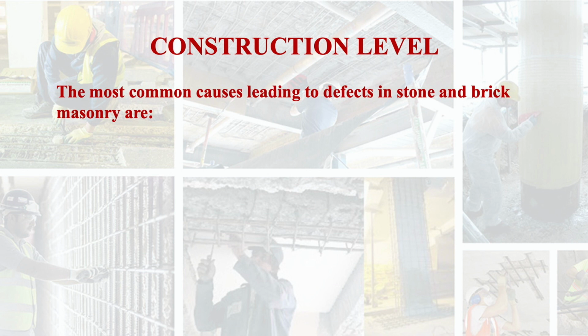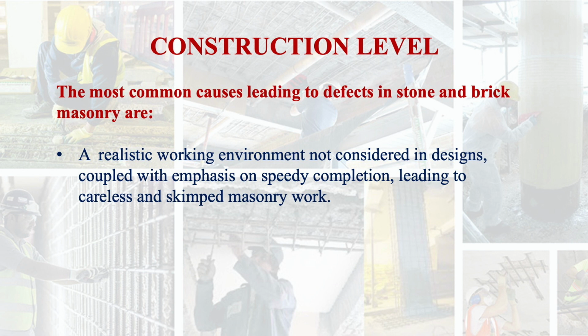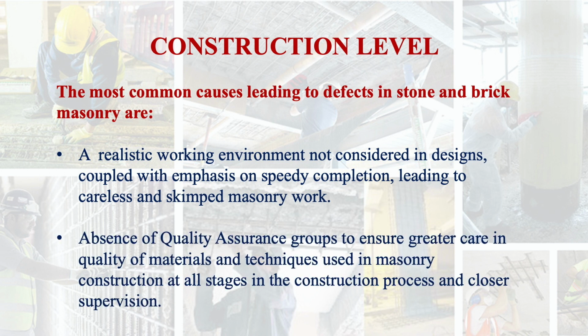Then construction level or construction stage. The most common causes leading to defects in stone and brick masonry are a realistic working environment not considered in designs, coupled with emphasis on speedy completion, leading to careless and skimped masonry work. Also, absence of quality assurance groups to ensure greater care in quality of materials and techniques used in masonry construction at all stages in the construction process and closer supervision.